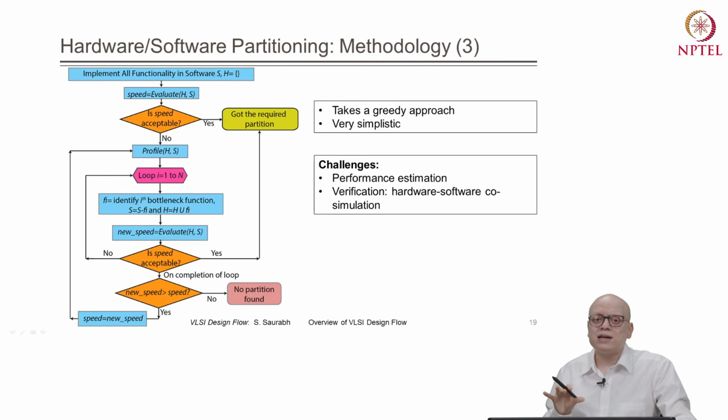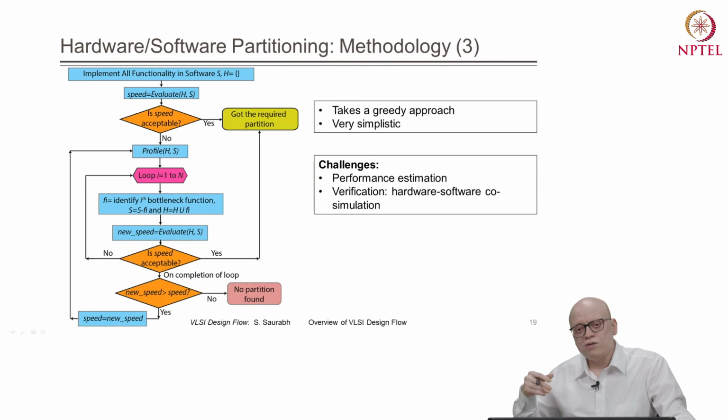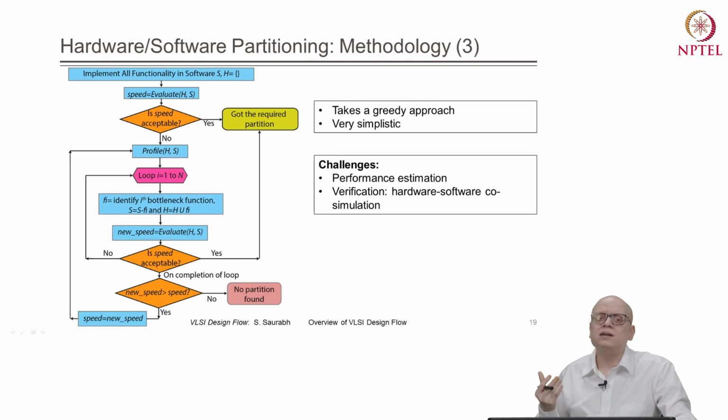The second approach is that we say the given function f1 is implemented in hardware, but we take it through a quick design flow. For example, we do behavior synthesis or high level synthesis, implement it, do placement, routing and other things at a very crude level, and estimate or get a number out of it, right? That can be another way to deal with this problem.